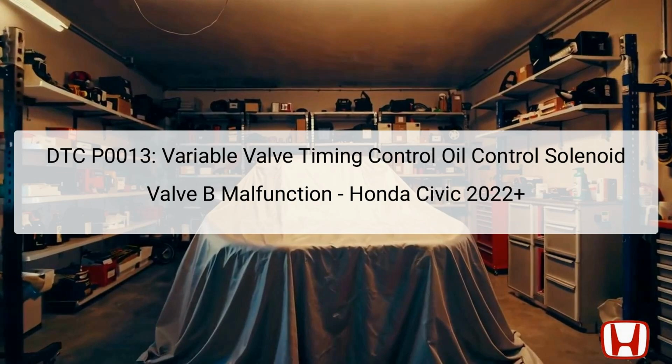It adjusts the timing of the intake and exhaust valves relative to the position of the crankshaft and camshaft. When the Engine Control Module, ECM, also known as the Powertrain Control Module, PCM, detects that the current received by the oil control solenoid valve B does not match the commanded specifications, it registers the DTC P0013. This indicates a fault within the VTC system, which may cause a number of performance issues.